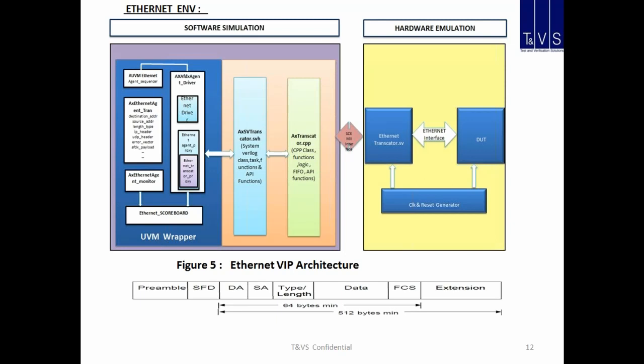And then the simulation environment has multiple UVM environments talking to those transactors. So you could have a PCIe, a USB, an Ethernet transactor all on the emulator, and then you can control the whole emulation through the software simulation by communicating to those transactors.